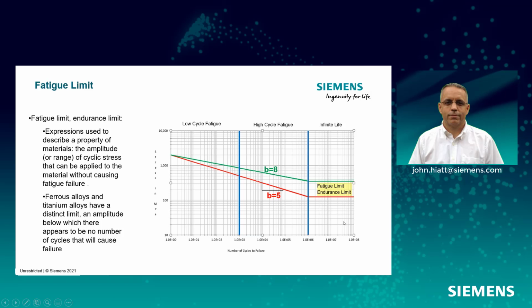One reason people do infinite life is that it's hard to count cycles. I see it done a lot in powertrain testing where something's rotating and there's getting loads every time it's rotating.